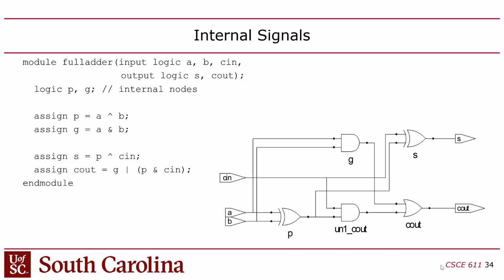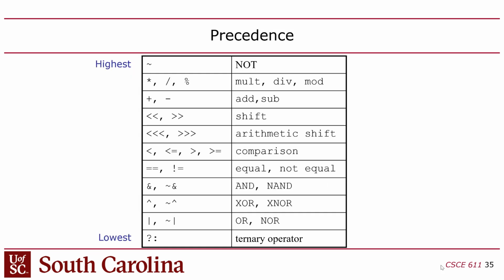So if I make a chip, I can put a circuit on there that has a delay linked to the technology and the fabrication process, and then I can measure that delay in terms of clock cycles. If someone made a knockoff of my chip, I might be able to tell because their ring oscillator is not the same speed as the original. So that's a PUF function. But anyway, it's getting to be a sidetrack.